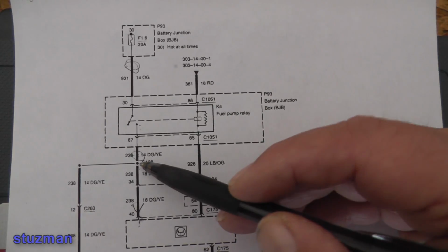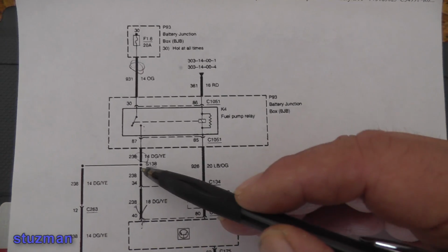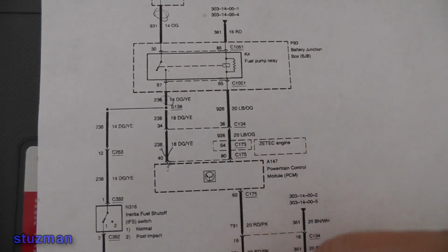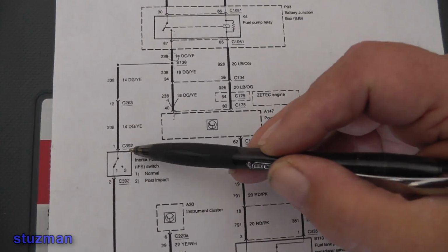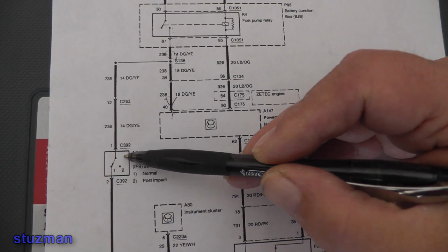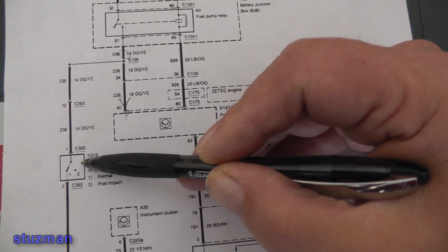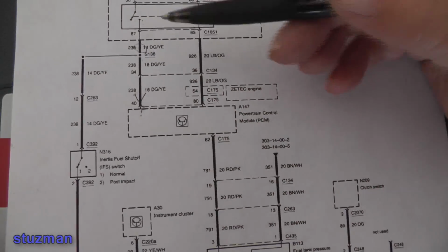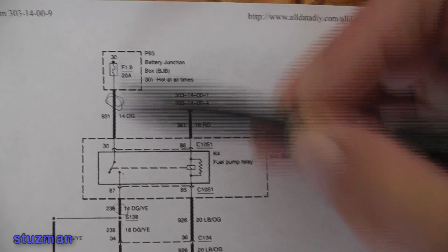So in a case like that, let's say this line was feeding injectors. Well, obviously, you want to be putting your clamp on this line, anywhere down here. So the best place probably would be right here at the inertia switch, which is located on the passenger side inside the cab, right behind a little access panel. So you could measure it right there. But in our case, since we have very little current right here, I'm going to be looking to measure it right up here. Okay? So let's get ready.